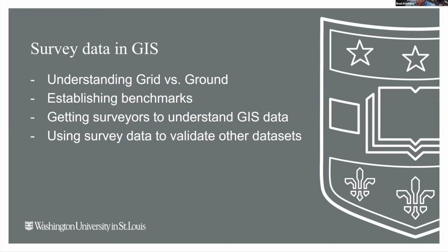And I'll show an example after I get done with these slides of how we use the survey data so that when we fly the drone, we're able to tie it in very accurately based on the manhole points that we use as ground control points to align everything. And then as a validation feature, after we process it, we put all the sidewalk lines down and they line up. They either line up or they don't, right? And we can test how accurate our data set is based on that, because we know that all the sidewalk line work was done from the survey.